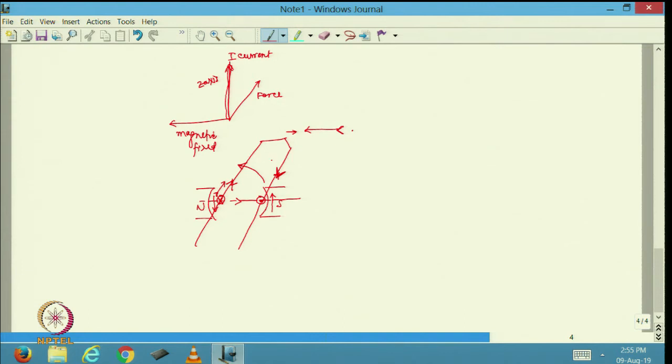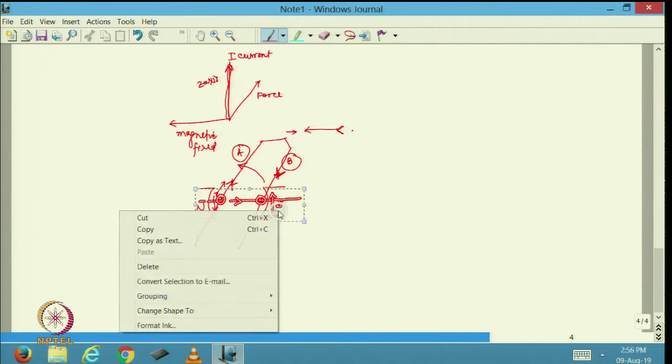So, the current, if I look at it actually along this, it is going to be an alternating current. If I call this conductor as A and this conductor as B, I am going to see an alternating current continuously going through B and A, because for some time I am going to see that B is under the influence of south pole.